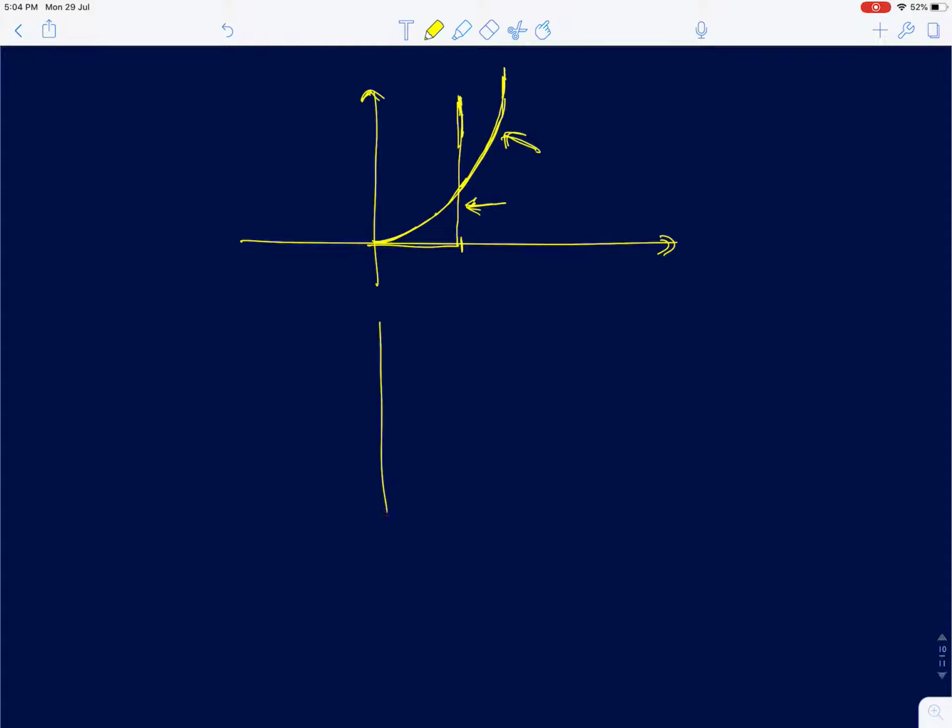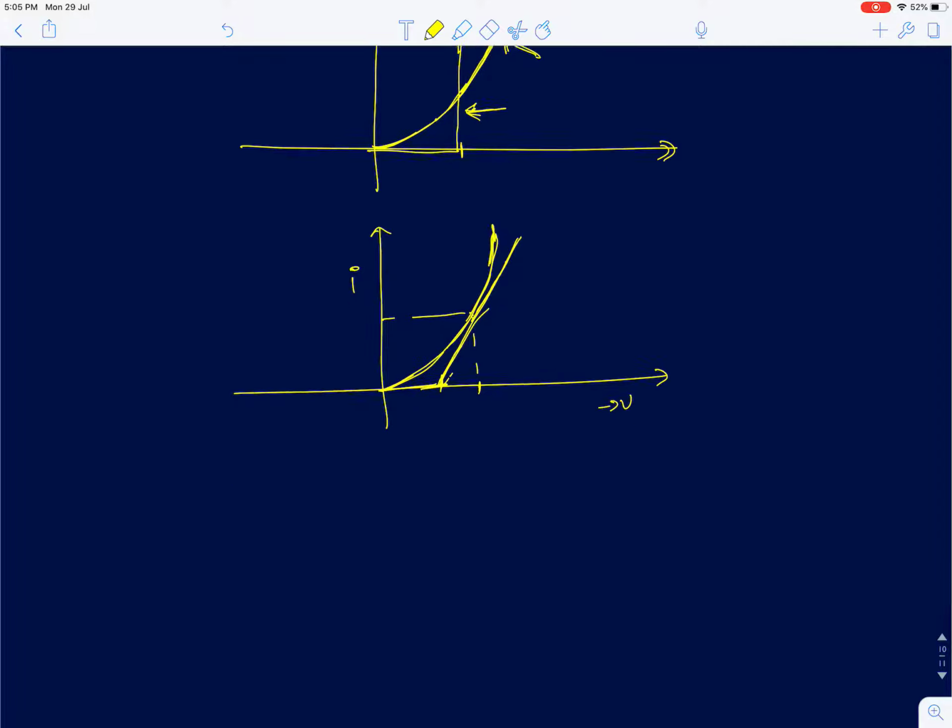So what you do is, as I said, again we have to use only linear circuit elements because it becomes difficult to solve nonlinear equations. That is the main purpose of going for models. So what we do is we start adding a resistor to the model in series with the voltage source. Instead of just modeling it as a cut-in voltage alone, we will model it with a resistor like this, such that the graph models the IV characteristics of a diode to a better accuracy.